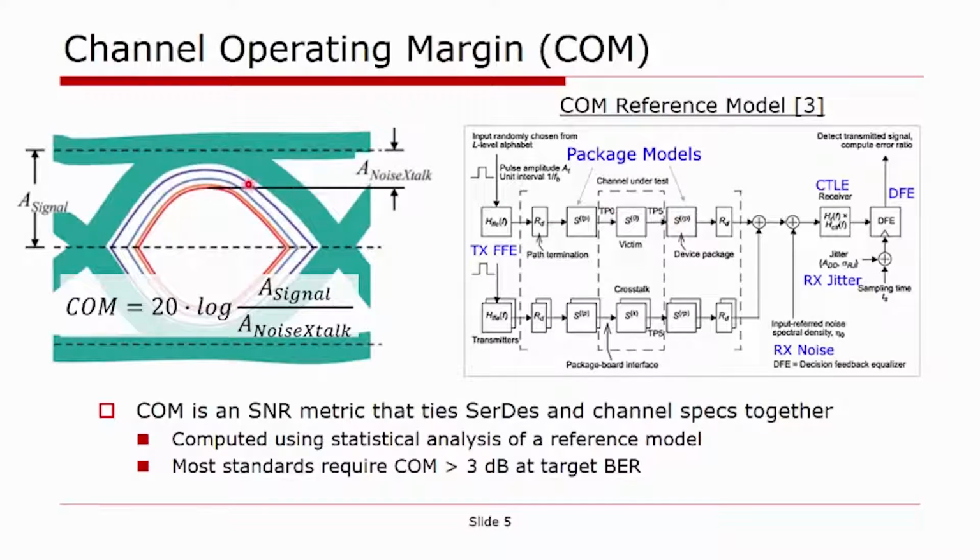Most of the subtleties in the COM calculation are embedded in the reference model that is used for computing it. Over the years, IEEE has developed a standardized reference model that everybody uses to get consistent COM results. That standardized reference model is shown on the right here. It includes abstractions of key elements on both the SERDES side and on the different components in the channel.